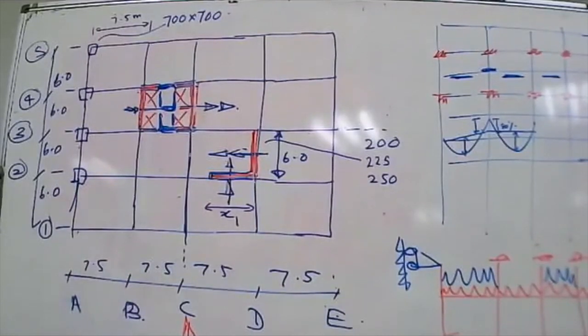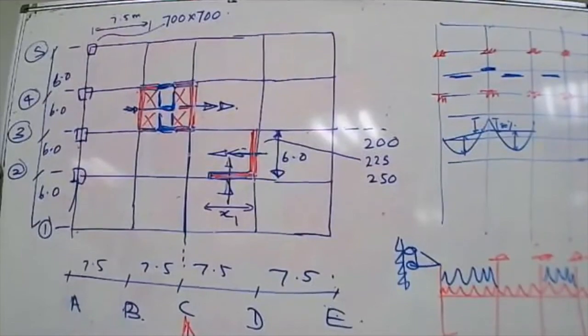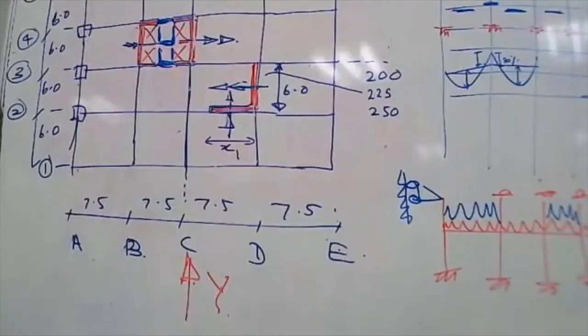Okay, sir. Thank you. Another question. Then you can confine the failure to the beam. Plasticity occurs in the beam, and the beam is okay because it has a higher capacity in the span section, so it's okay to have the plastic hinge forming in the beam. But if the plastic hinge forms in the column, it can start moving and losing stability. Yeah, exactly. Yes, sir. A bigger column and a smaller beam.